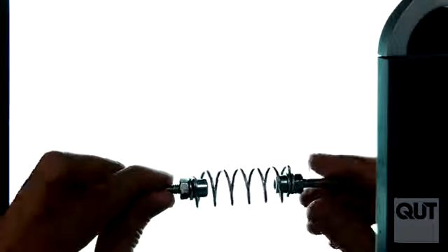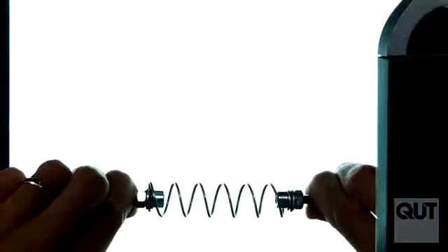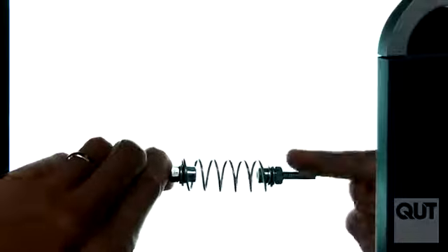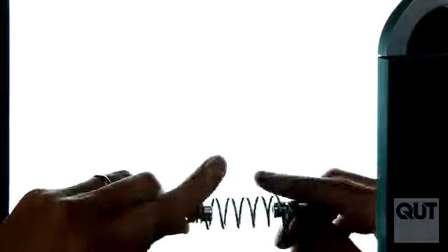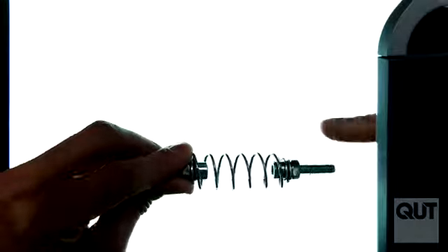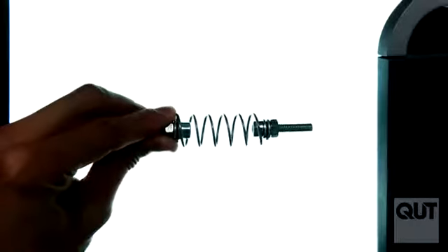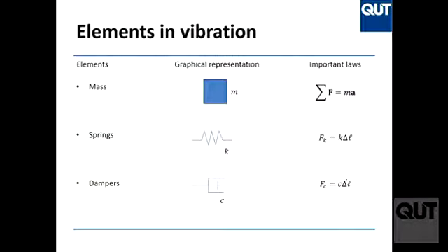Okay. So this is the spring. If I pull it this way, the spring is pulling my hand back towards the center of the spring. If I compress the spring, so if I move that way, the force is given to me that way. Okay? So the force that the spring gives back is opposite to the direction in which you are squeezing it or pulling it. Okay? Clear? Same thing for the damper, obviously. If you pull the damper, it will pull you back. If you push the damper, you squeeze the damper, it will resist your squeezing. Okay? Putting a force the other way. All right.